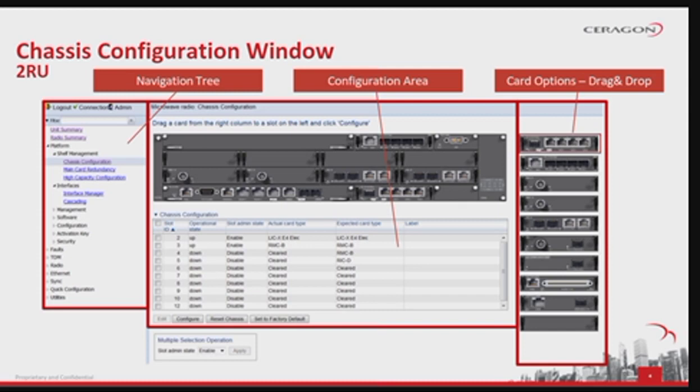For our example, that gigabit line interface card can only be used in slots 2 and 12 from the unit. Slots numbering starts from 1, in the lower left, continues to right and then up. So, slots 2 and 12 are the ones next to the power distribution cards.